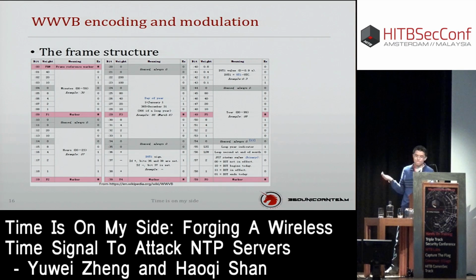It sends one frame at the start of each minute. Each frame consists of 60 bits. If it transmits 1 bit per second, the frame starts with a marker bit and also sends a marker bit every 10 seconds. To reduce error,